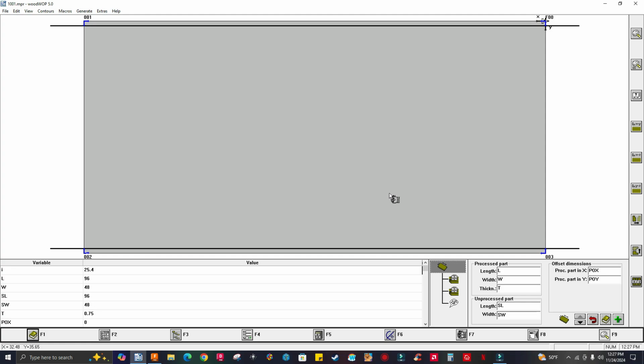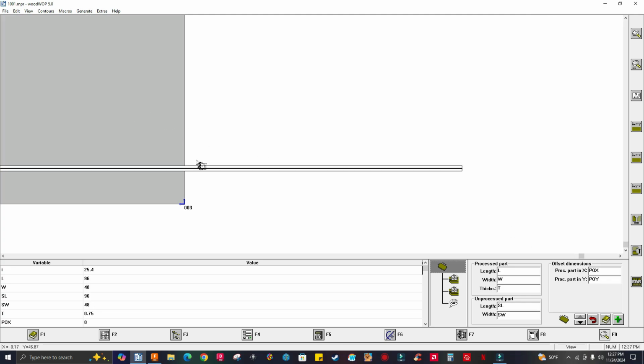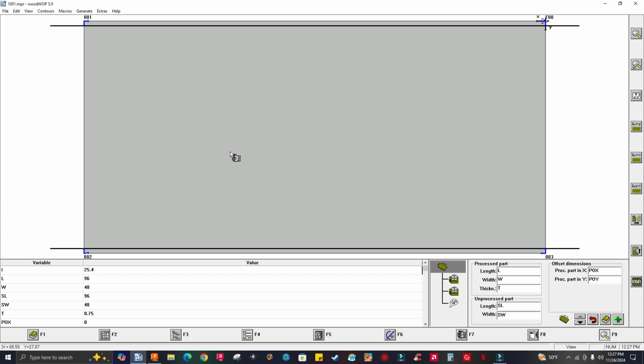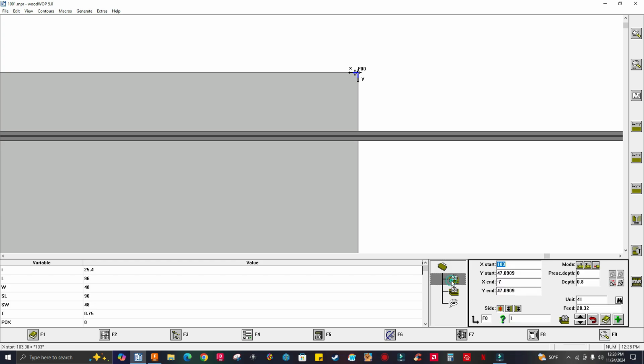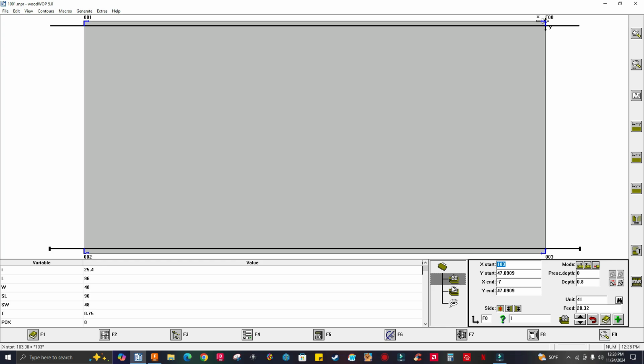But you always have to make sure it's cutting all the way through. So let me check the first one in the front. I'm zooming in, drawing a window to zoom in. So it's cutting through here. Let me double right click on it to zoom out. But you see the one in the back is not cutting all the way through. That's the first saw blade macro. See, I got the right depth here, 0.8 inches, right? Because depth is measured from top to bottom, and Z dimension is from bottom to top. Okay, that's the difference, right?